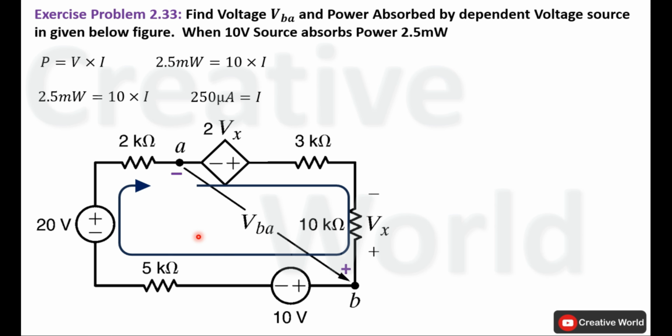Up to this point, we have identified the direction of current inside this closed loop circuit along with its magnitude. Now we have to make polarity notation across these two resistive elements according to the direction of current. We know that current entering terminals are taken with positive sign and current leaving terminals are taken with negative sign in the light of passive sign convention.